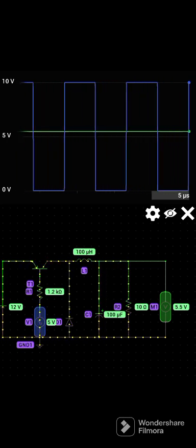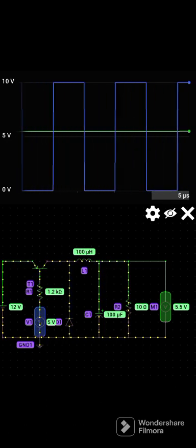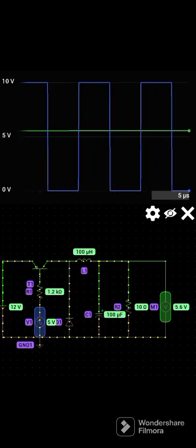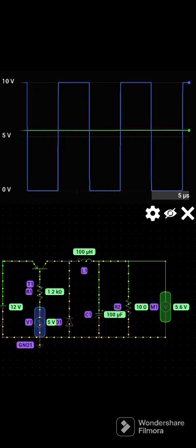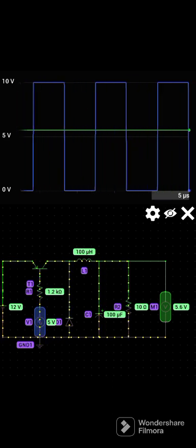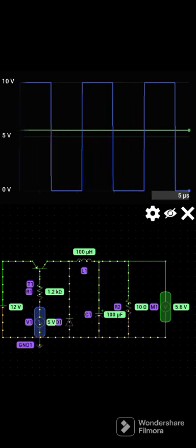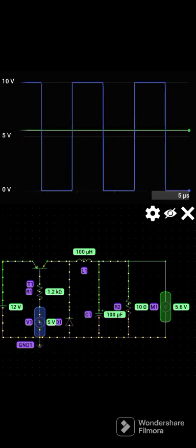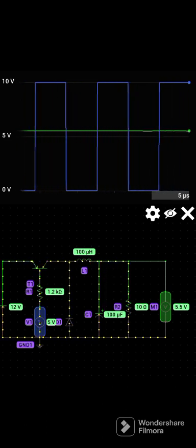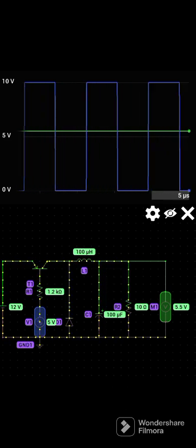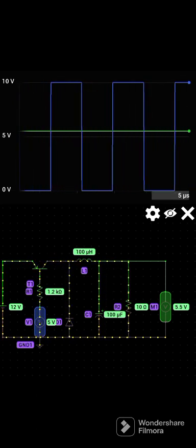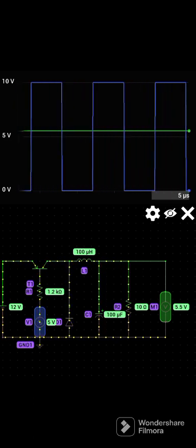at a lower voltage than the input voltage. Now, this circuit has the basic elements of a simple buck converter circuit. We need a switching element, that's a transistor. We have an inductor and a capacitor, that is the output capacitor. The switching element is usually a transistor, as I have already said, a MOSFET. It can be controlled by a PWM, that is pulse width modulation, signal. The signal controls the duty cycle of this switching element, in turn controlling the average output voltage.